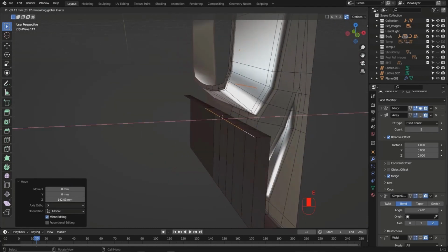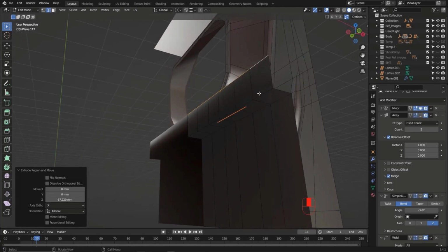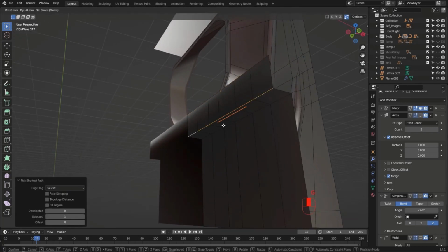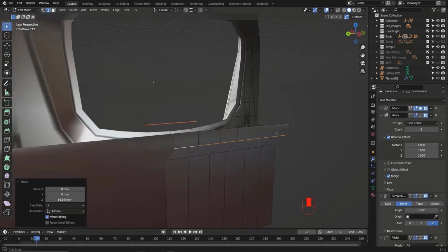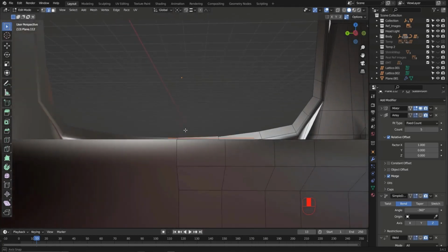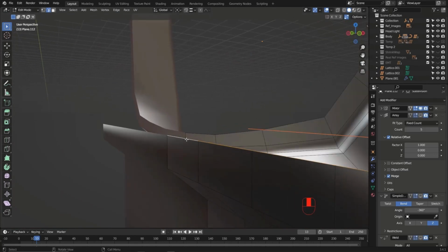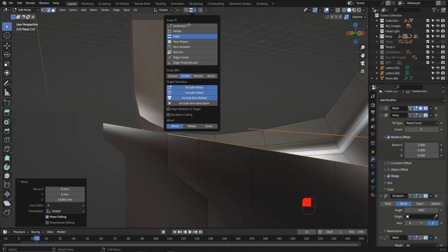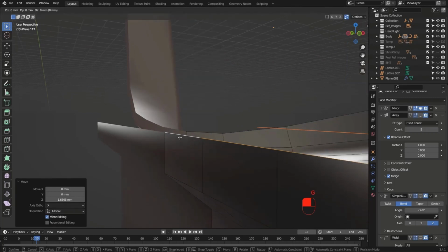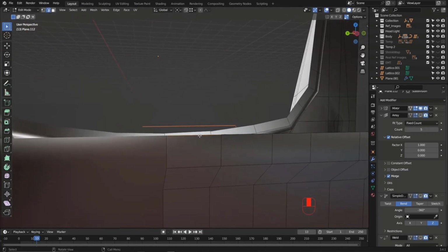And extrude those again. And extrude those up like that. You can grab this and hit G to the Z and move them like that. That will work. It's okay. And maybe I can merge, or let's grab these edges, hit G to the Z and align it with this vertex. You can use vertex tab, G to the Z again and hold control and align it. Grab this with this, you can merge them, hit F.